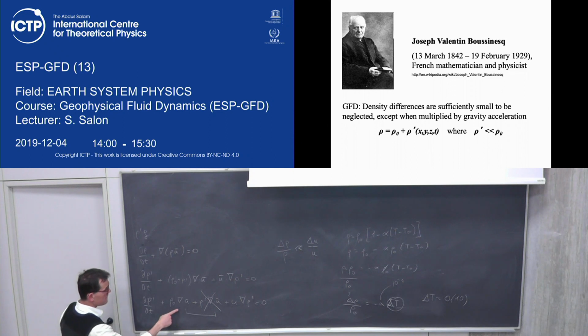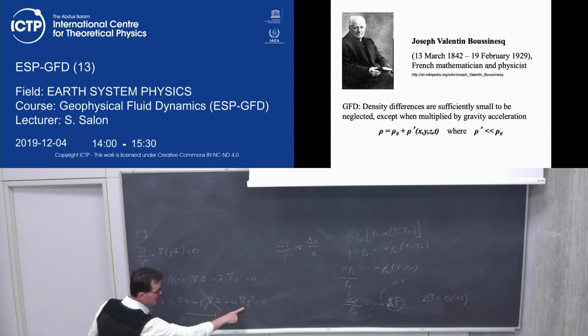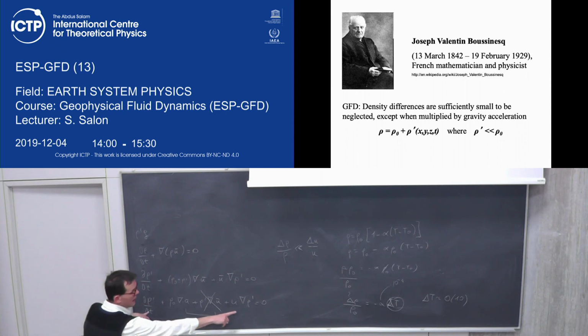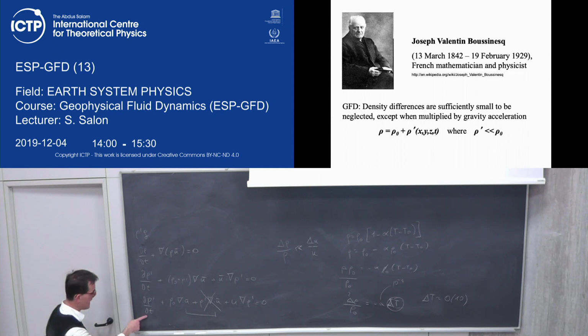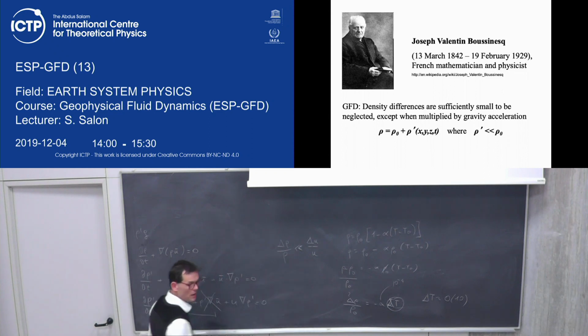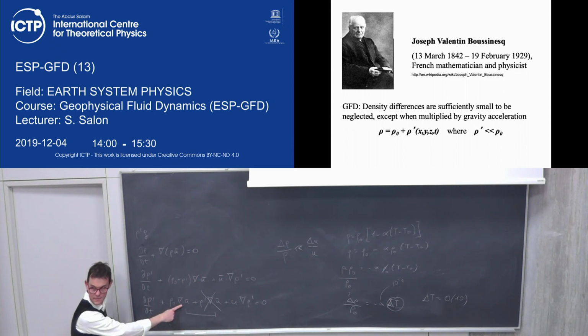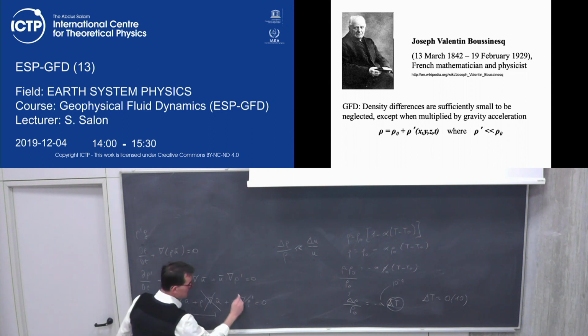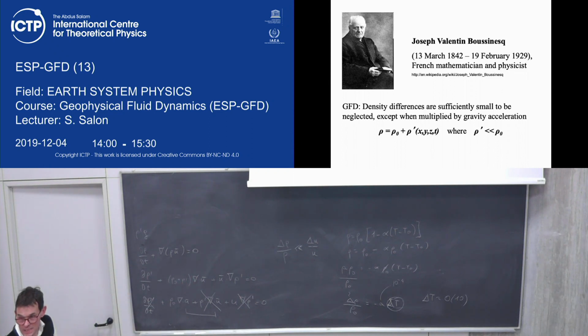And if I, again, compare this term to this term, these two terms are variation of density in time and in space. But we have said that variation of density is much smaller than variation of velocity. So these two terms actually can be neglected. Of course, this is an approximation, okay? It's not exactly 0. So I'm taking a sort of scale analysis. So which is the dominant term in this equation? It appears that the dominant term is this one.